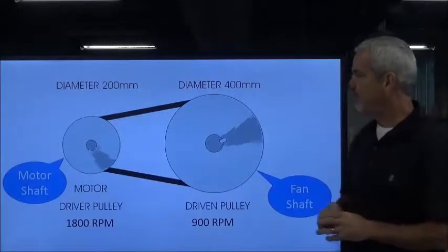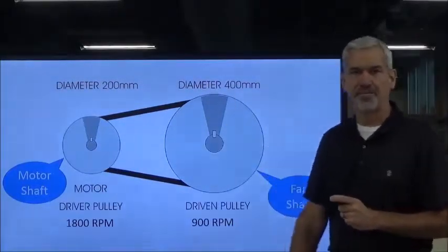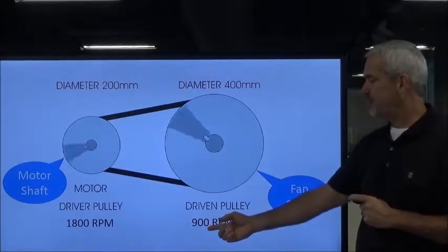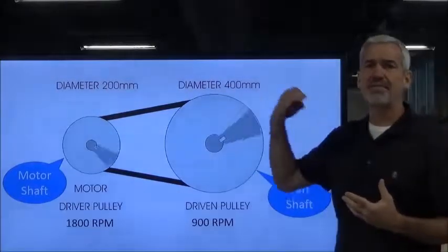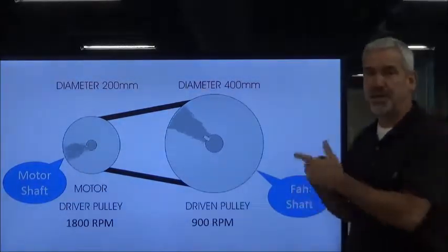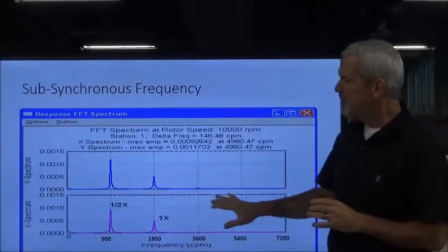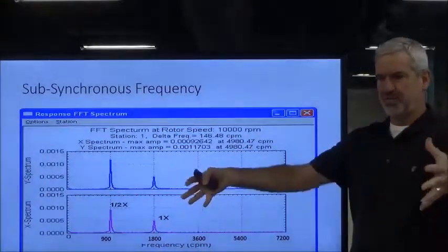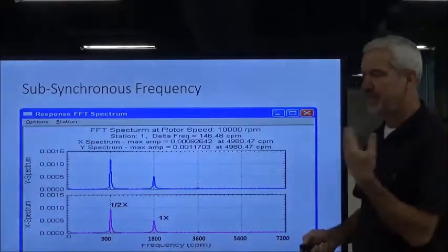And going to our previous example, we go ahead and dial in on the fan. We can eliminate the motor. And the fact that the frequency is heaviest at 900 RPM, we can eliminate bearings too, because they're going to have a higher frequency because they've got multiple balls spinning in there. We'll get into that a little bit too. But this spectrum, we look and say, okay, what runs at 900 RPM on this blower unit right here? Well, the fan does, so we just dial in on that and we eliminate all the other stuff.